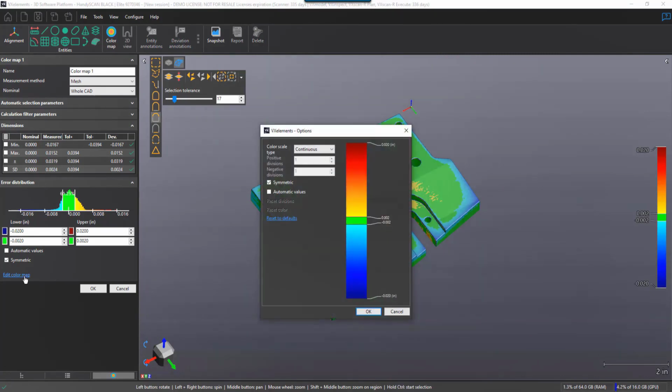In the area distribution, we can say edit color map, and currently it's a continuous gradation of color with the plus or minus 2000 in there. We can change that to discrete as well, and you can see incrementally we've got currently 9 positive divisions and 9 negative divisions in the color bar. And you can see that it divides that range of the 2000 incrementally with the numbers.